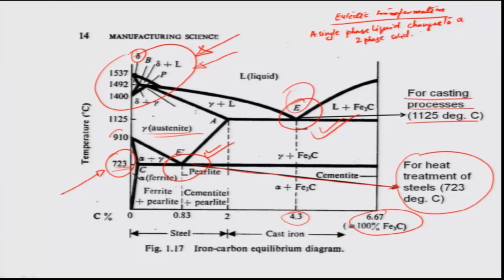If you remember, in the ice salt diagram, we talked about salt water, which was completely uniform and homogenized, and it freezes below minus 22 degrees Celsius at a certain percentage of salt, and that structure, although not distinguishable, is two phase. So salt is entrapped homogeneously within the ice crystals.